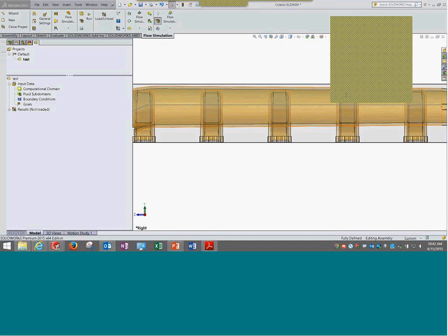Okay, then we can change the value of environmental pressure. Is it the same as static pressure? As I told you, environmental pressure is more of an initial condition, a starting point for the fluid flow. The values you are changing there are just telling it the initial condition. Whereas static pressure, the way we use it in the software, is nothing but an enforcement. That is, we are telling the software that irrespective of any other changes, the pressure at the surface remains what we give. That's it. So that works, Simon.